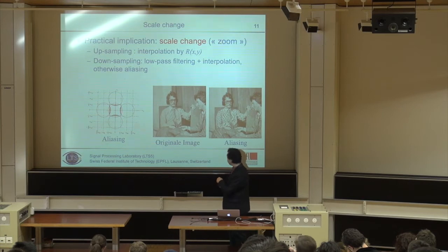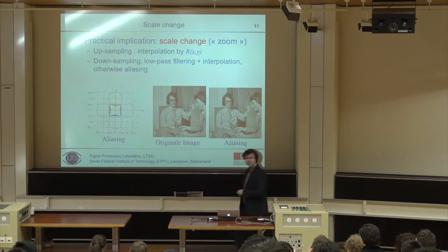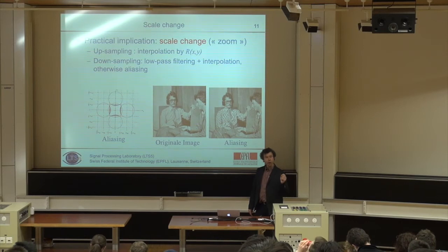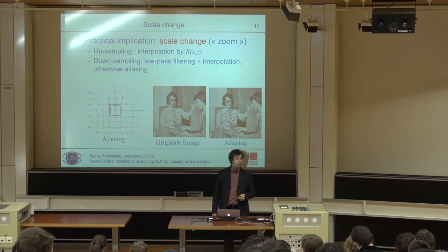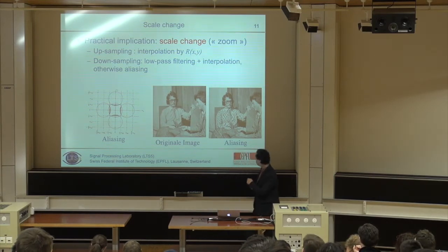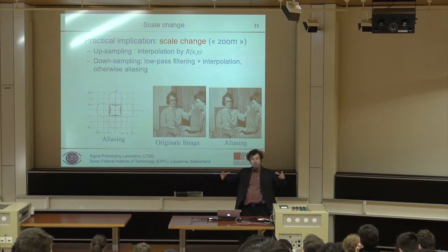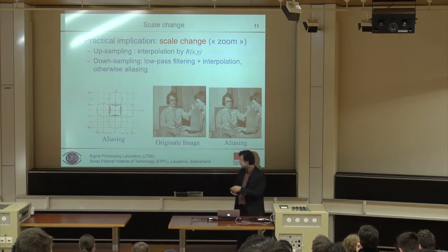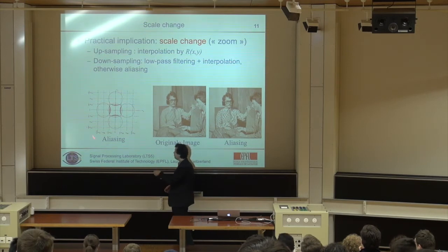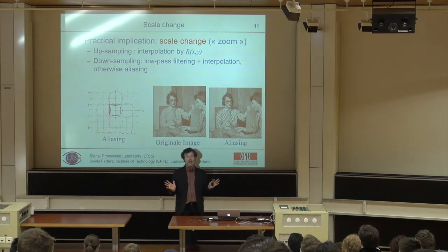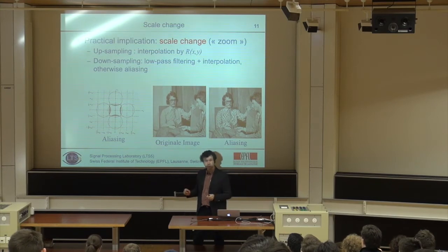And so basically from an image like that, if you decrease its size without caring, if you take 1 point every second point, so if you basically throw away 1 point every second point and reconstruct the lower size image, okay, I stretched it to have the same size, but it's a lower size image, basically the replicas of the spectrum will come closer to each other. You will have basically in the spectrum of your image the appearance of replicas of the other spectra. This is the typical aliasing, right? Typical thing that you have in 1D as well.